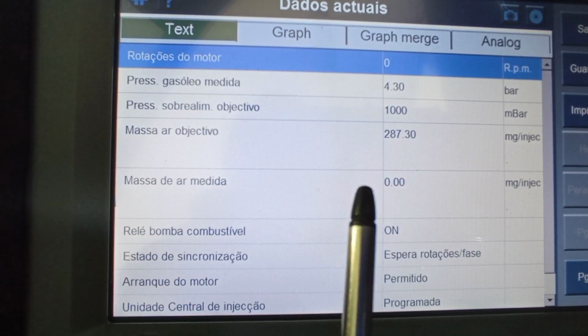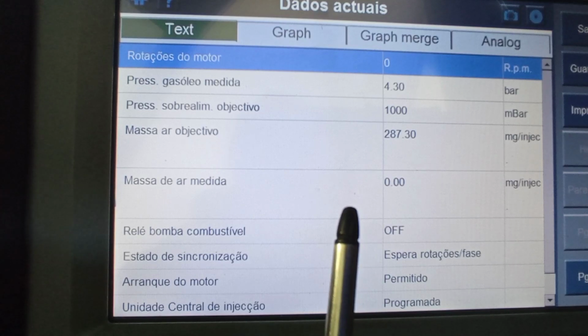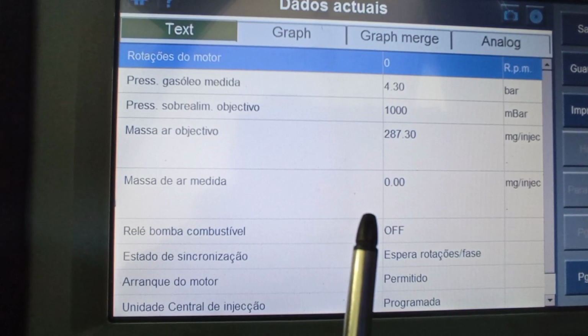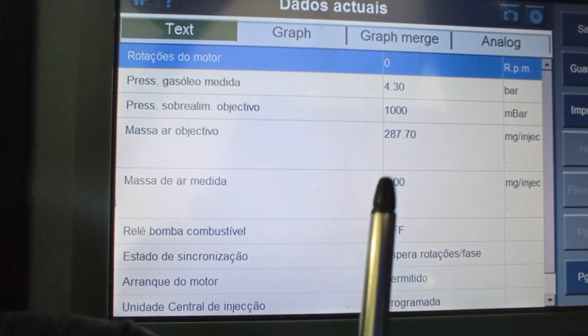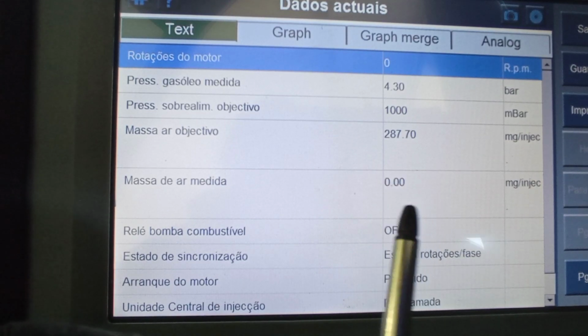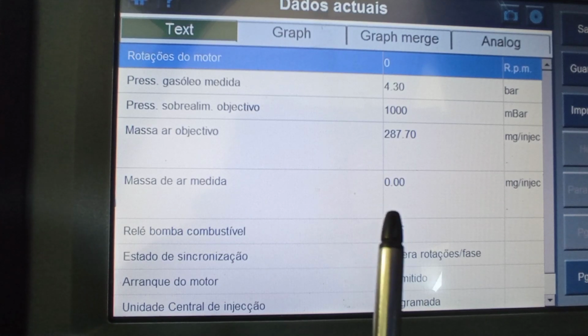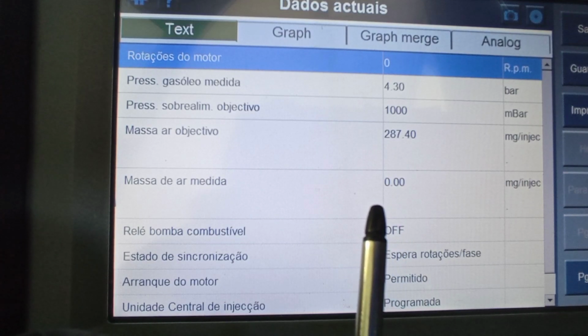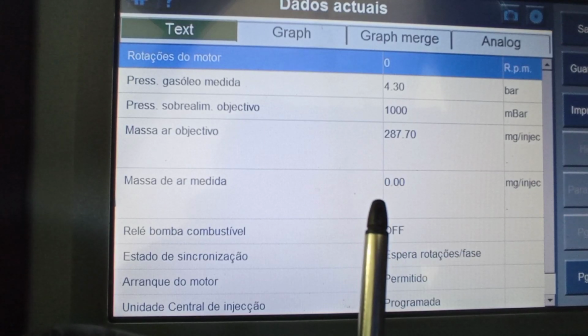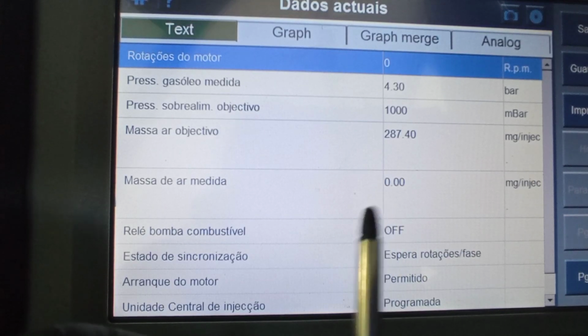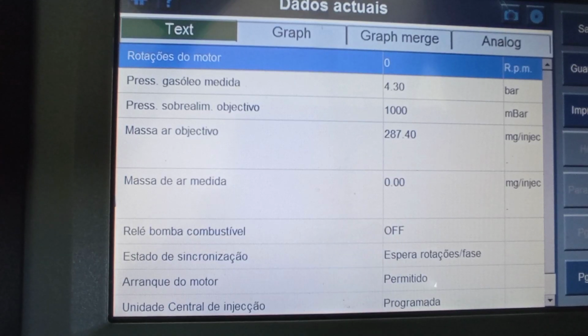What happens is, for some, namely the 1.3, the Iveco engines, for example, they really need the airflow in order to start the car, in order to stay at idle even, okay? So if you burst an intercooler pipe and then your car does not work, that is only because of your intercooler pipe, okay? So check that out and then just connect your pipe and the car will start, okay?